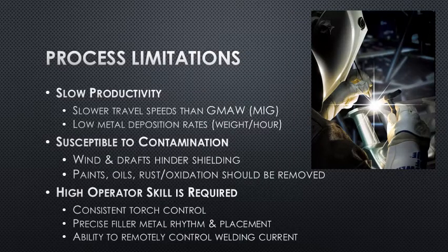The TIG process does have some limitations, and they begin first and foremost with the fact that it's relatively slow in terms of productivity. Travel speeds are slower than with MIG welding.